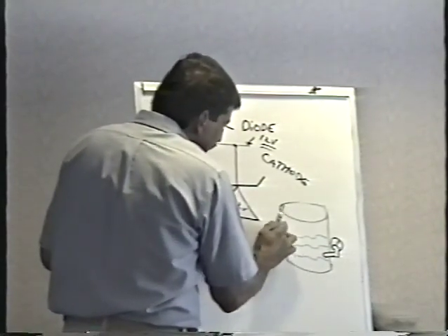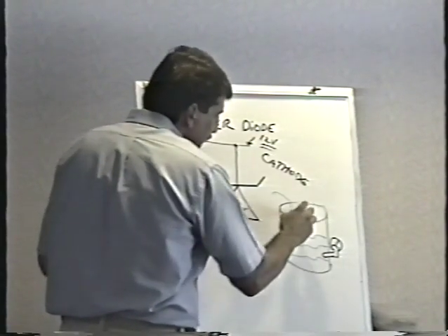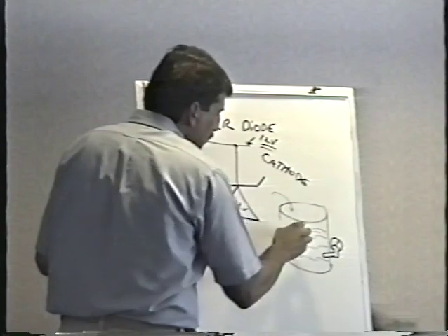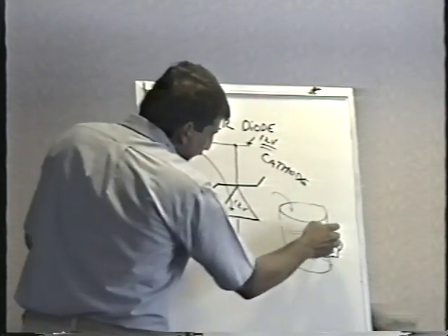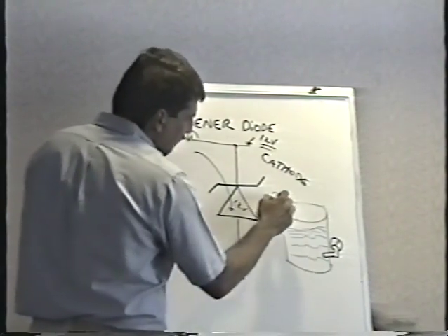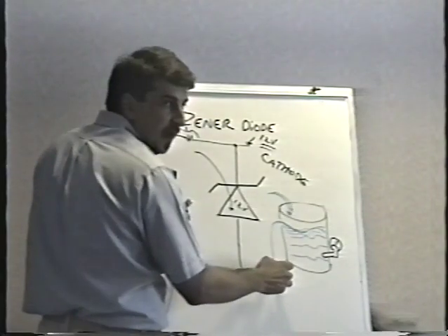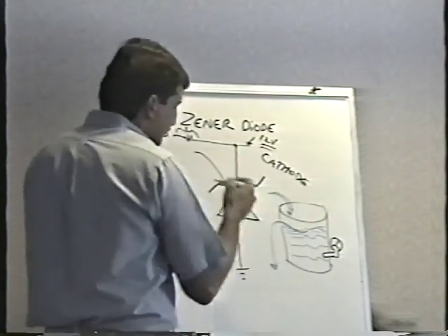I've got a hole here in the side of the tank. I add more water to it, the pressure goes up. Add more water to it, pressure goes up. At this point, if I add any more water to it, I can't get the pressure to go up any higher, can I? Because if I add extra water to it, it's just going to flow out the hole and land on the ground, right? The pressure is fixed.